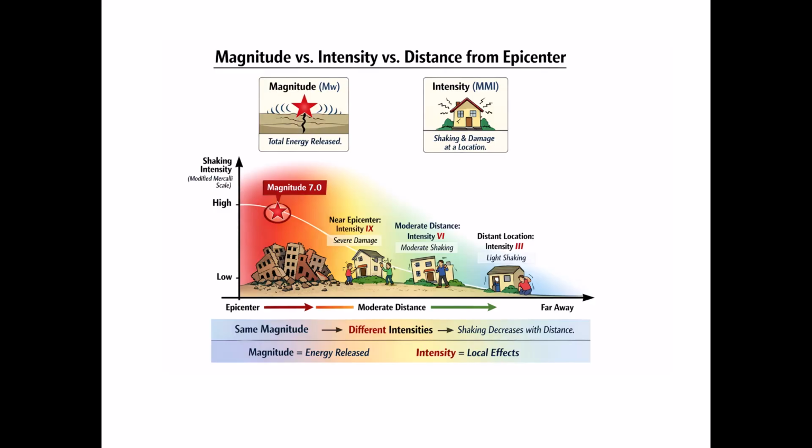And we're going to be talking about some metrics like peak ground acceleration, for example, that are measured with accelerometers or other seismic instruments, and those are at point sources that measure what's happening at a given location, and heavily dependent, for example, on what we call the soil as well. So there's a whole branch of this we're going to talk about called structure-soil interaction. So the soil effects can amplify energy, and we'll definitely be talking about that.